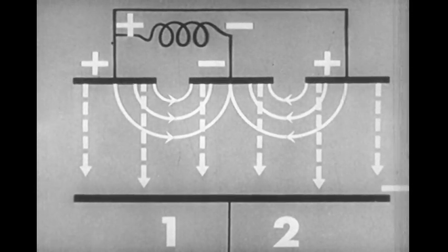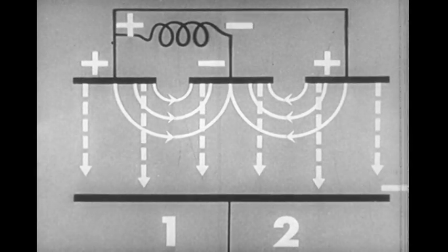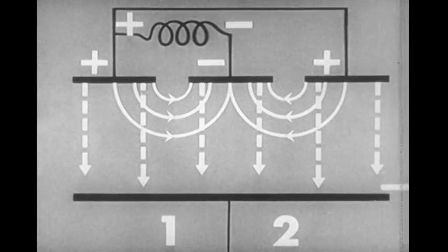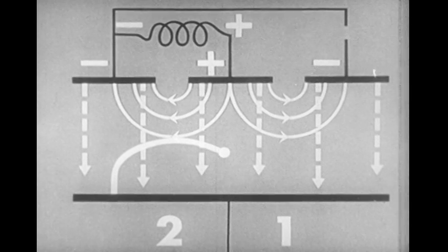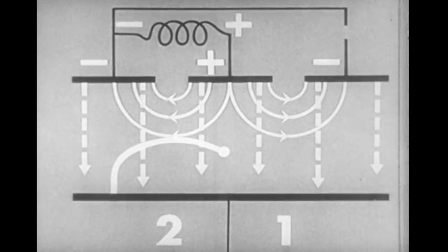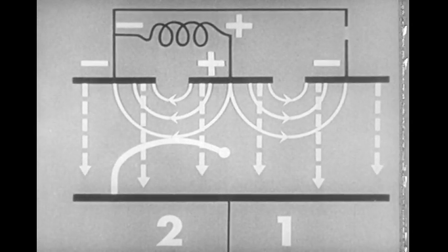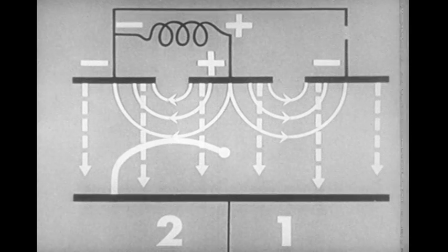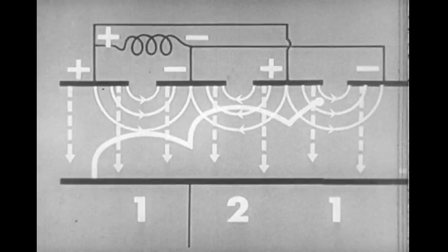The energy given up by the electrons to the RF field will change the polarity of those fields, so that at the end of one half cycle, the RF fields will be reversed. Thus, the electron, which has completed one half cycle in region 1, will now strike region 2 in the proper phase relationship to give energy to that RF field. This process will continue until the electron eventually reaches the anode.